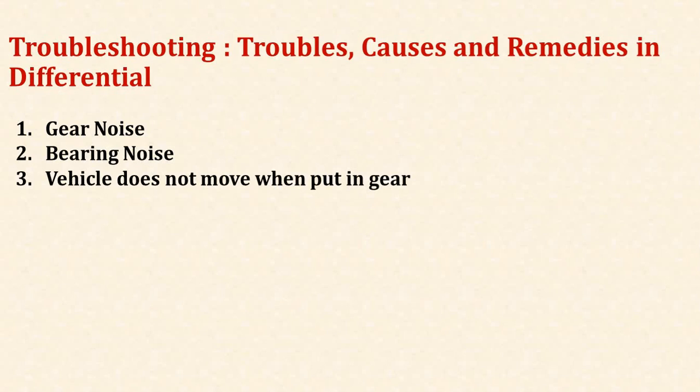For the remedy, we have to adjust it properly. Then another cause of gear noise is improper tooth contact in mesh between the drive pinion and ring gear. For that, the remedy is to adjust or replace.